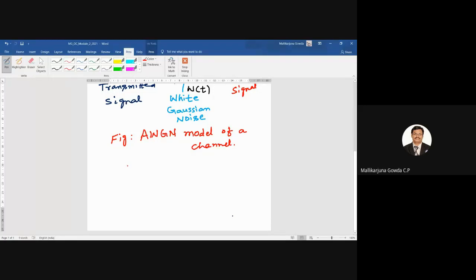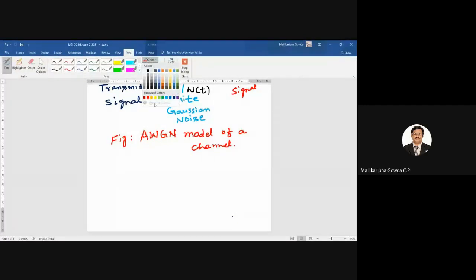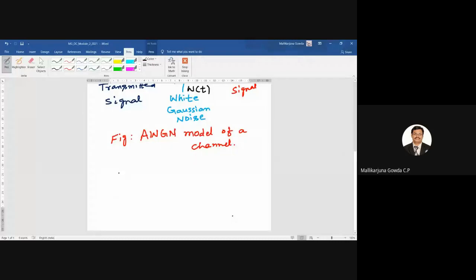Then I think we have discussed the analyzer. Does anybody remember the analyzer? What is the analyzer? Synthesizer and analyzer, two things I discussed, right? Maybe even in the first module and the second module, I represented Si of t. How do I represent that? It is a summation of, j is 1 to n, Sij phi j of t, right? How do I get those coefficients Sij, that is Si1, Si2, and so on up to Sin, where Si of t is the input signal?